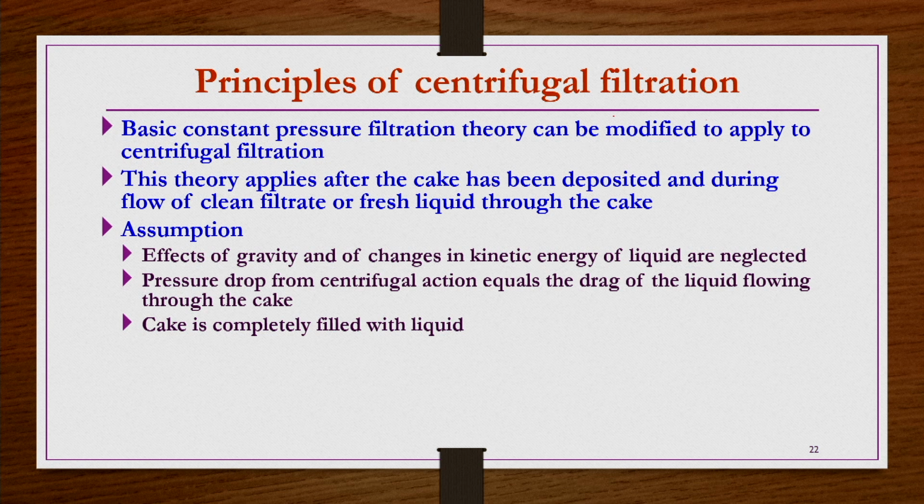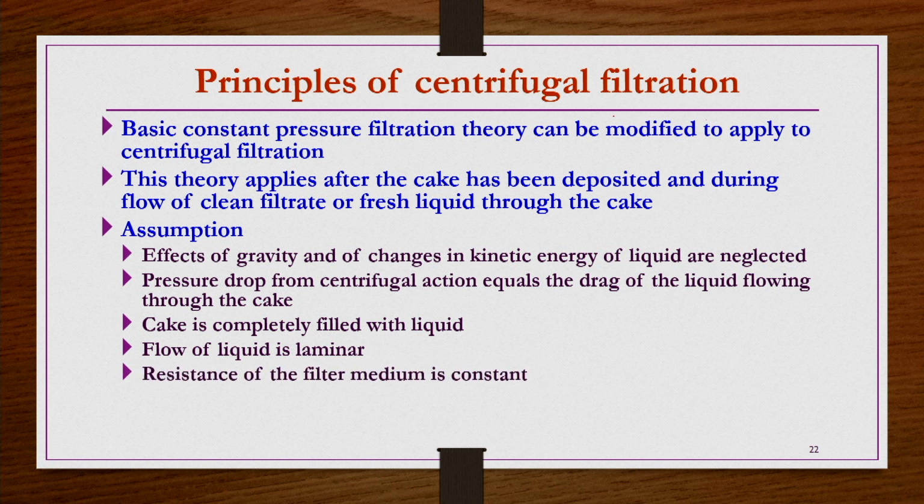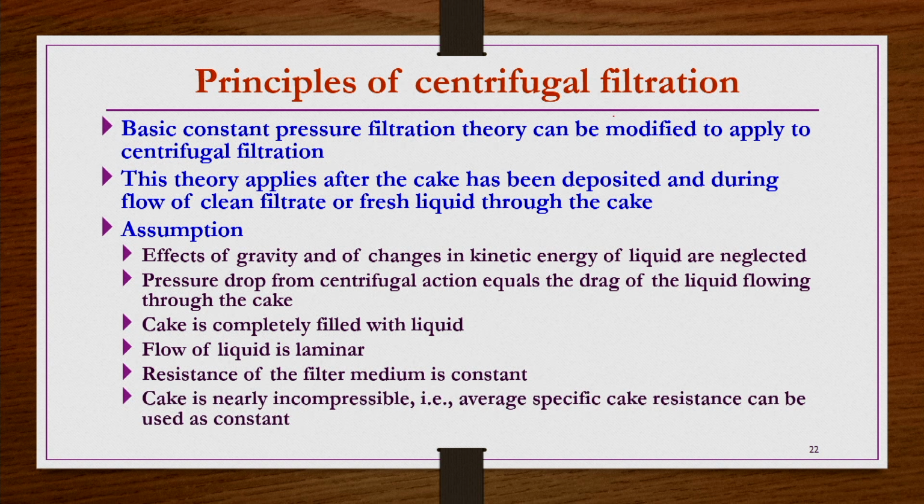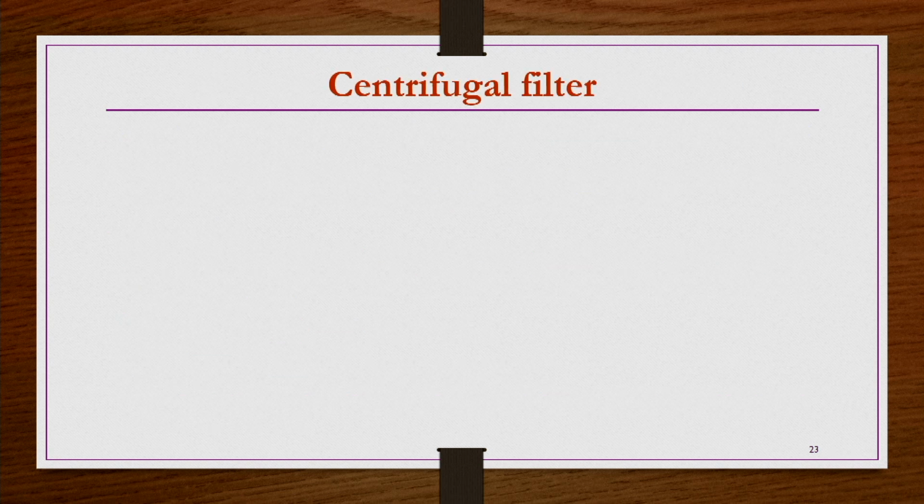Cake is completely filled with liquid. So, the interstitial spaces between the particles within the cake are not free, they are always occupied by liquid. The flow of liquid is laminar, and the resistance of the filter medium is constant, it is not changing. Cake is nearly incompressible, that is, the average specific cake resistance should be used as a constant value. Okay. These are some of the assumptions.